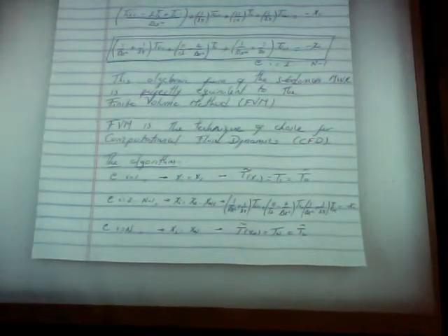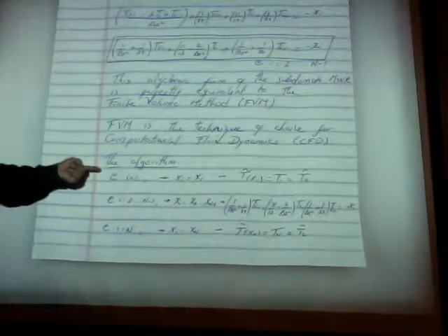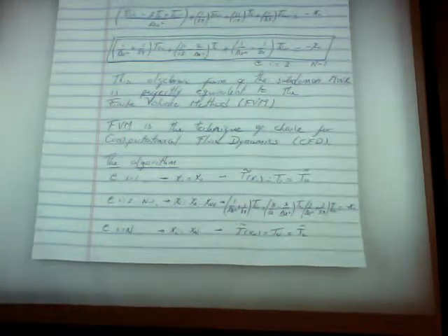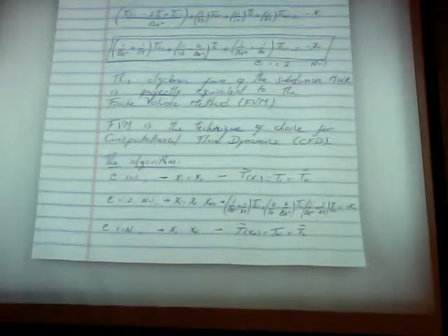So what if, for example, in the first node, a flux is applied instead of a temperature? How will you deal with that? Having a temperature applied, the first kind boundary condition at the first node, makes this very simple, because we can get T1 as just an imposed condition. We need an extra equation that relates the temperature at 1 to something else. So, let's see.